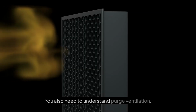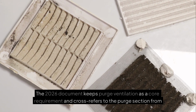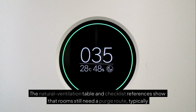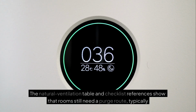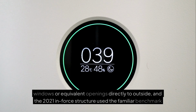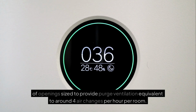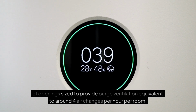You also need to understand purge ventilation. The 2026 document keeps purge ventilation as a core requirement and cross-refers to the purge section from later system-specific guidance. The natural ventilation table and checklist references show that rooms still need a purge route, typically windows or equivalent openings directly to outside, and the 2021 enforced structure used the familiar benchmark of opening size to provide purge ventilation equivalent to around 4 air changes per hour per room.